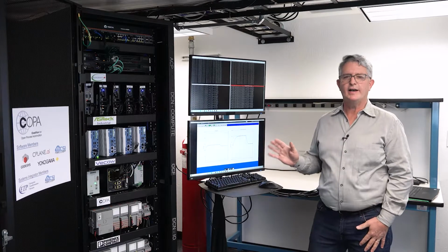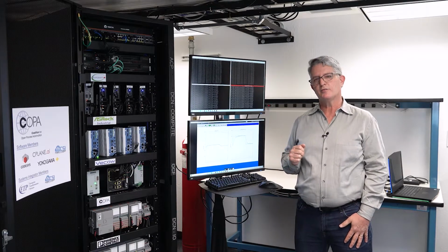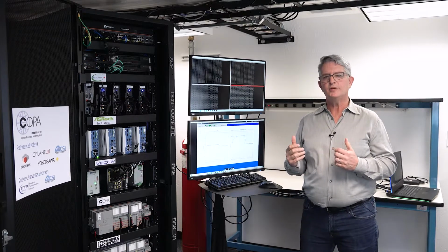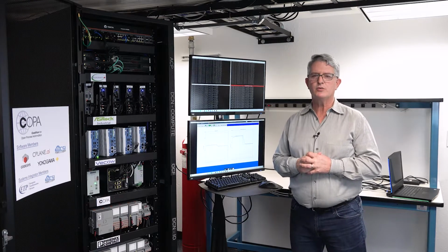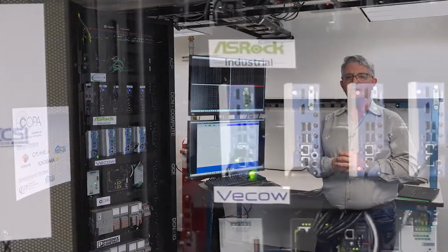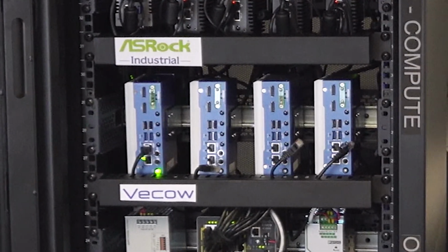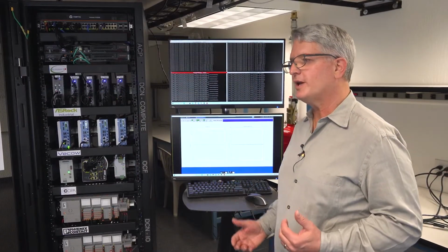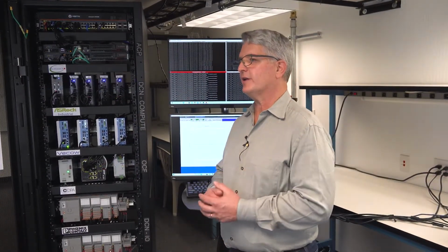This modern technique of high availability using software and virtualization can provide fault tolerance to most use cases. And it's proven to be equally reliable and vastly less expensive than redundant hardware. Another significant feature of an OPAS-based architecture is the ability to evolve and upgrade the control system even after plant commissioning. Let me demonstrate this for you now by adding and discovering new devices to incorporate them into your control strategy. As Tom mentioned earlier, being able to upgrade the compute capabilities without touching the I/O is a significant benefit.